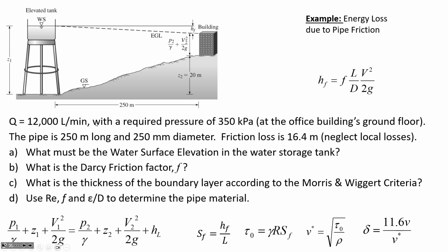So the fluid velocity is Q divided by A. If we want to know what's the speed of the water on average traveling through the pipe, we have 0.2 cubic meters per second divided by 0.04909 square meters. So the water is flowing through that conduit at a velocity of 4.074 meters per second. That's pretty fast. It's moving along through that pipe.